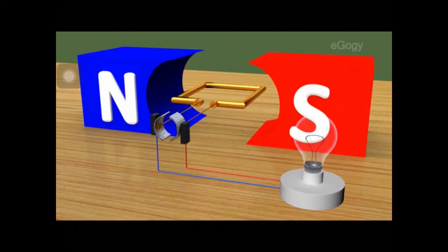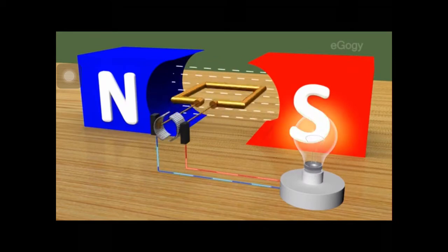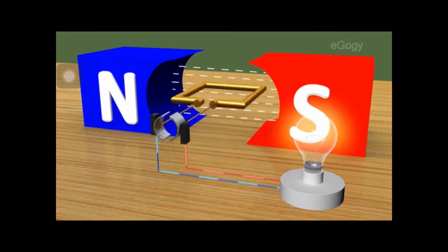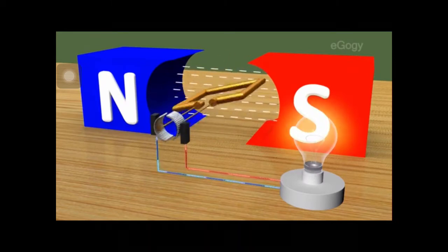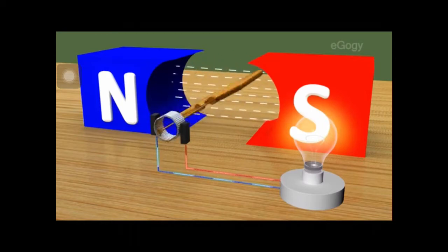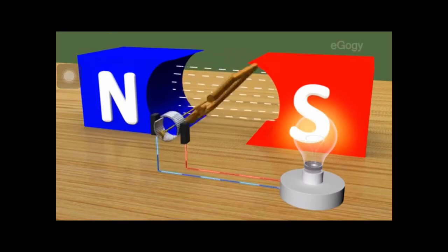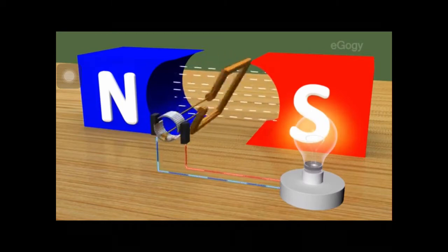Today's topic, we're going to be talking about the DC generator. To start off with, what is a DC generator? A DC generator is a rotating machine that supplies electrical output with unidirectional voltage and current. The field is produced by direct current in field coils or by permanent magnets on the stator. The output or armature windings are placed in slots in a cylindrical iron rotor.